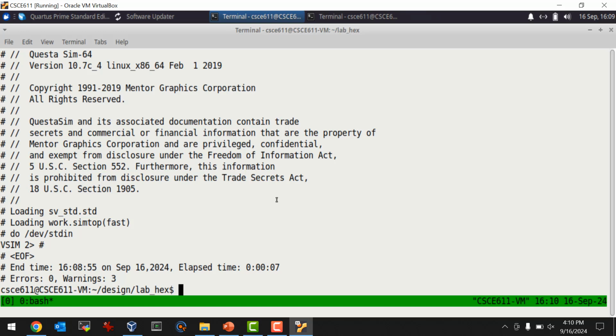Actually, that's really your only choice if your design works in simulation and doesn't work on the FPGA. How often does that happen? Not very often, but it can happen. So if everything checks out in simulation, you put it on the FPGA and you got a paperweight, then you're going to have to use Signal Tap. But we can help you out with that in the lab. I used to talk about it in lecture, but hardly anyone uses it.